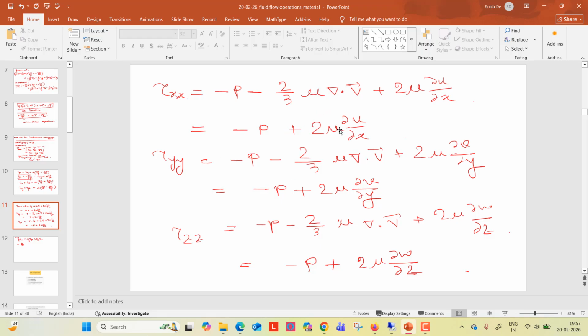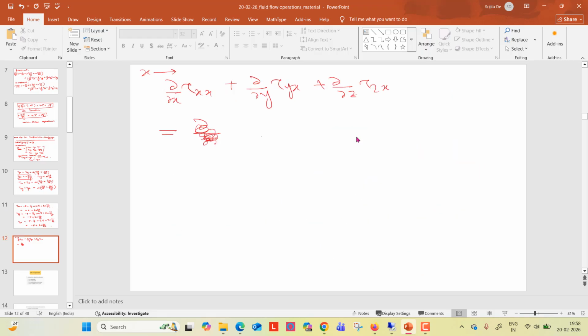So it will be del del x of minus p plus 2 mu del u del x. So what will it be? It will be minus del p del x, right? Minus del p del x plus 2 mu del 2u del x2, right?